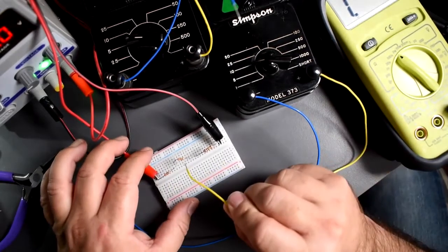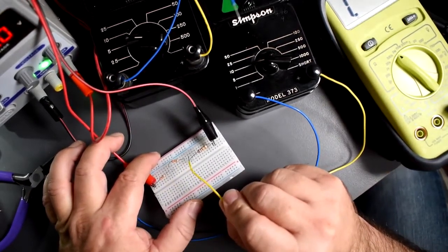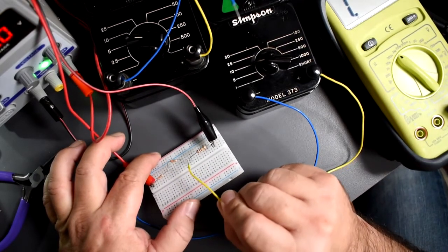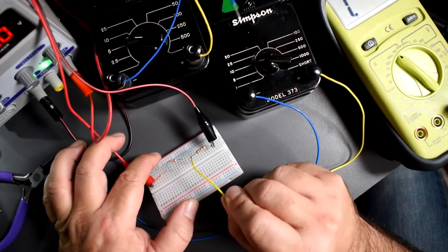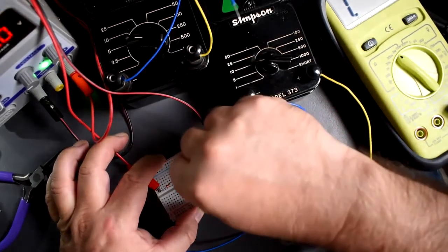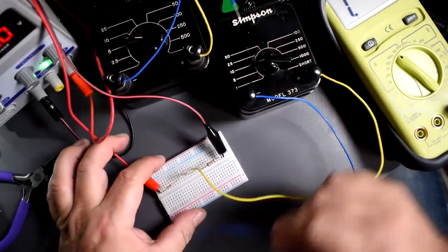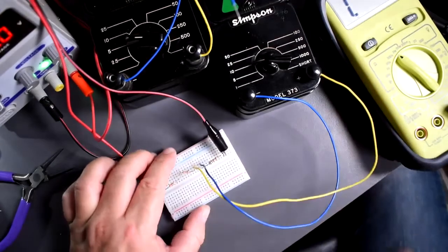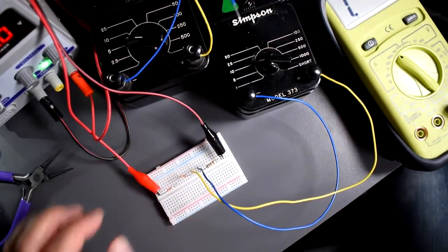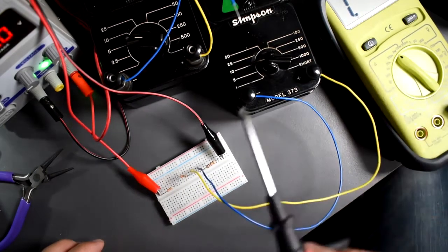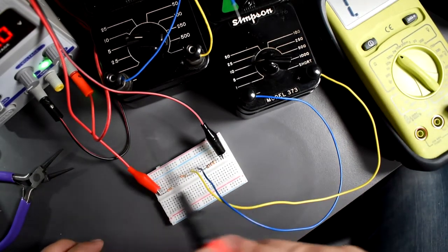So over here, when the circuit is broken, this would be the positive side of the circuit, and there's a break right here, and this is the negative side of the circuit. So just match the polarities. Okay, I'm going to put this one here, and we're going to put the negative right here. So now we have a current flow that goes from the power supply through this resistor, through that resistor, through the amp meter, and then through this resistor, and comes back to the power supply.